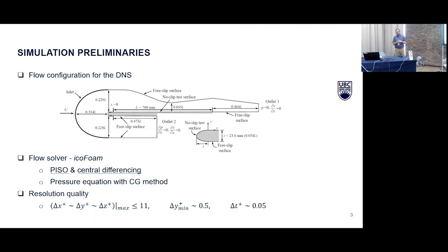One other comment is I used a relatively bulgy leading edge. The leading edge diameter to length is about, I think, 8%. The numbers are here, so one could calculate it, but I forget if it's 8% or 5%. For a low pressure turbine blade, that's kind of thick. More akin to what you would have on a high pressure turbine, which are thicker because there's integral cooling inside of the high pressure turbine. Low pressure turbines are generally a little bit thinner, and so it's more of a sharper leading edge.